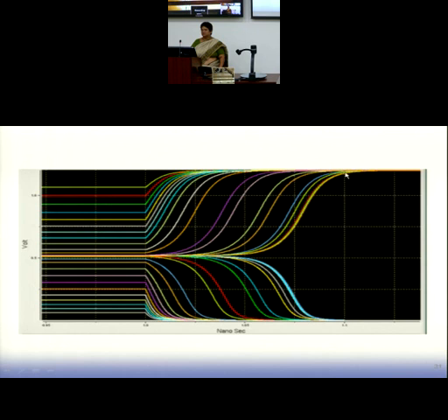Whereas if you are closer to VIH, very soon it stabilizes to a high value, and if you are closer to VIL, very soon it stabilizes to the 0 value. So wherever you are at t equal to 0 will decide how much time you are going to take. And the problem comes when you are somewhere in the middle.